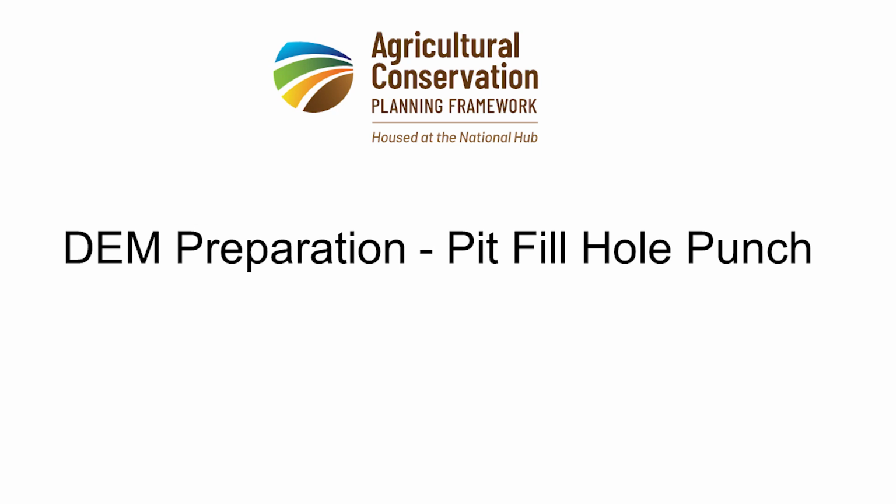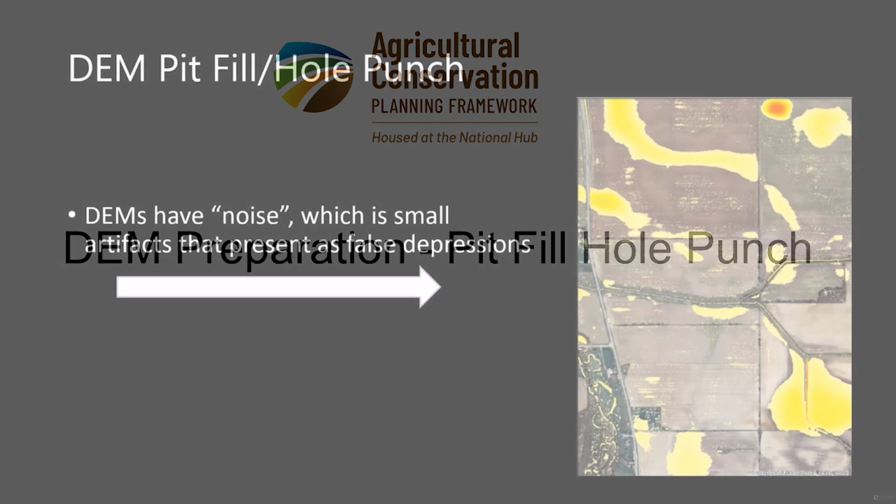Hello, my name is Josh Obrecht, and I am a GIS analyst with the ACPF National Hub. In this video, we'll go over how to run the Pit Fill Hole Punch tool.